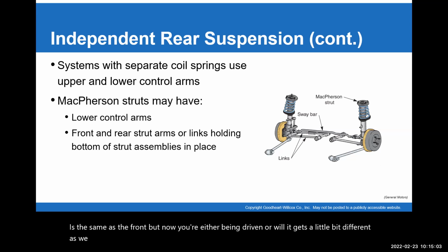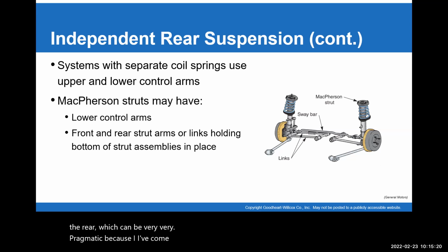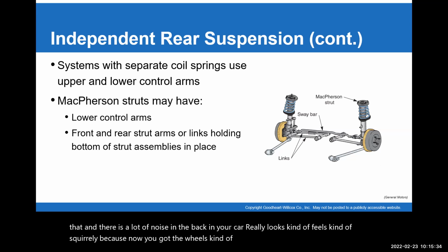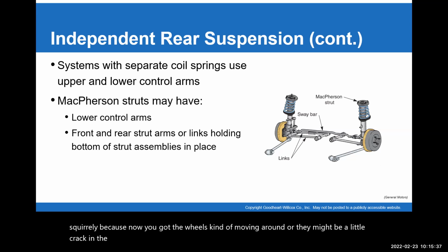Sometimes they call them a dead axle, or a solid axle system on the rear, which can be very problematic, because I've come across where the actual solid axle snaps and breaks, and there's a lot of noise in the back, and the car feels kind of squirrely, because now you've got the wheels moving around, or there might be a little crack in the rear axle.